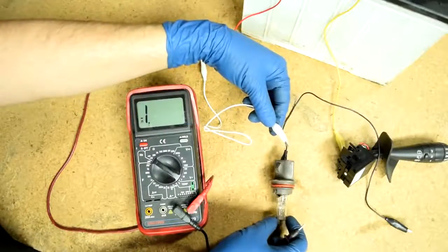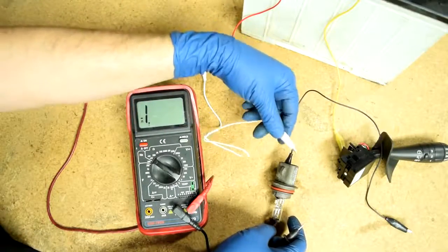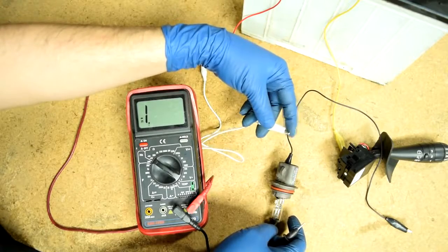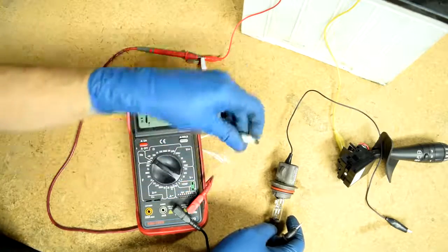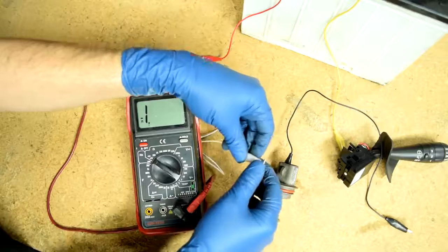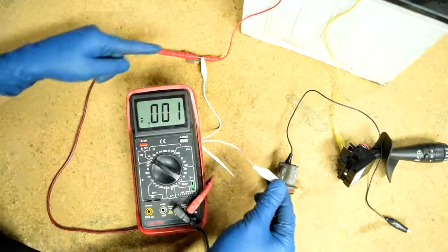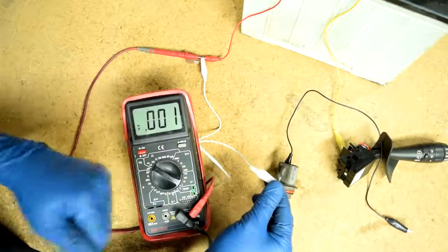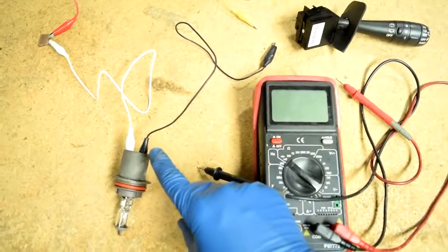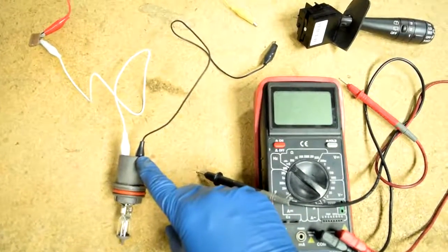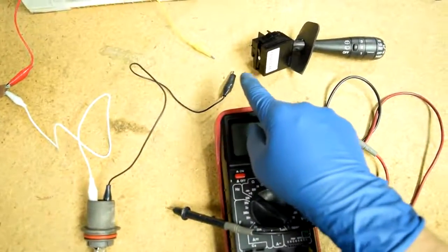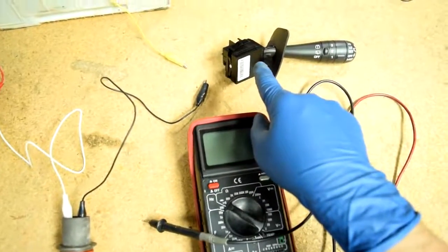So next you would go to your light bulb and remove the connector, and then identify the right wire that's coming from your fuse box by looking at a wiring diagram, and then just do a continuity test from the fuse box to the connector. And then you would have to perform the same procedure from the connector for your light bulb to the wire that goes to your headlight switch.